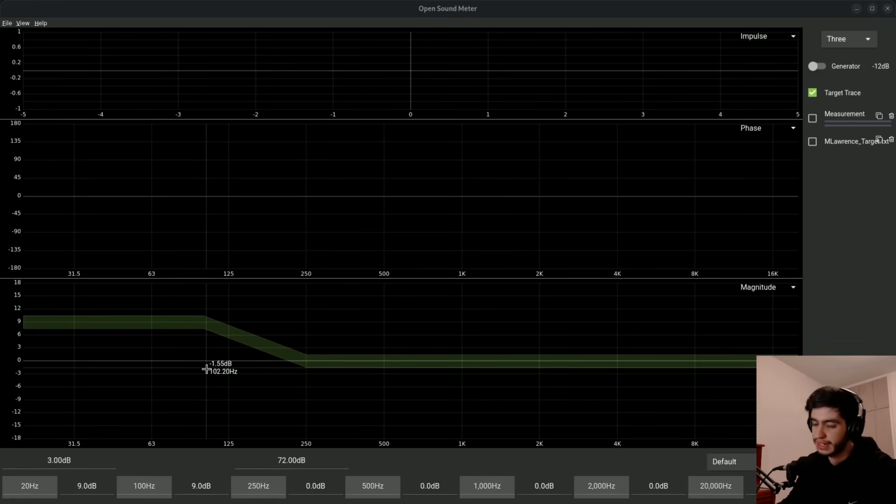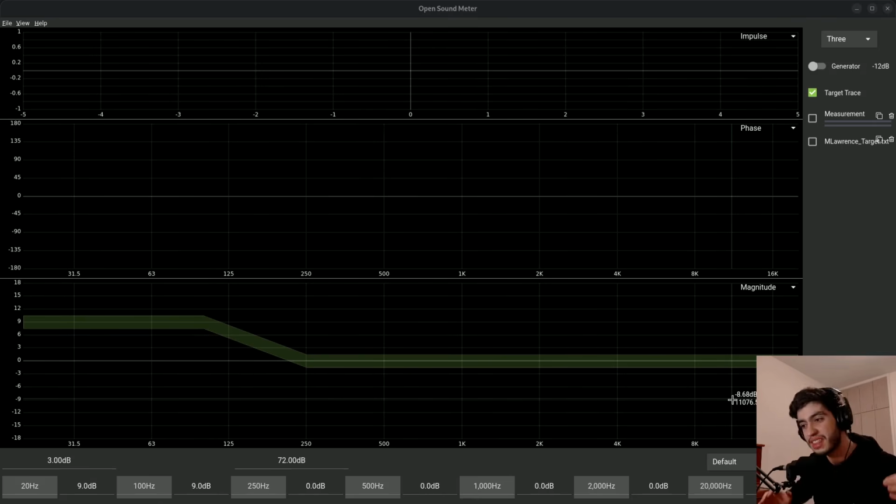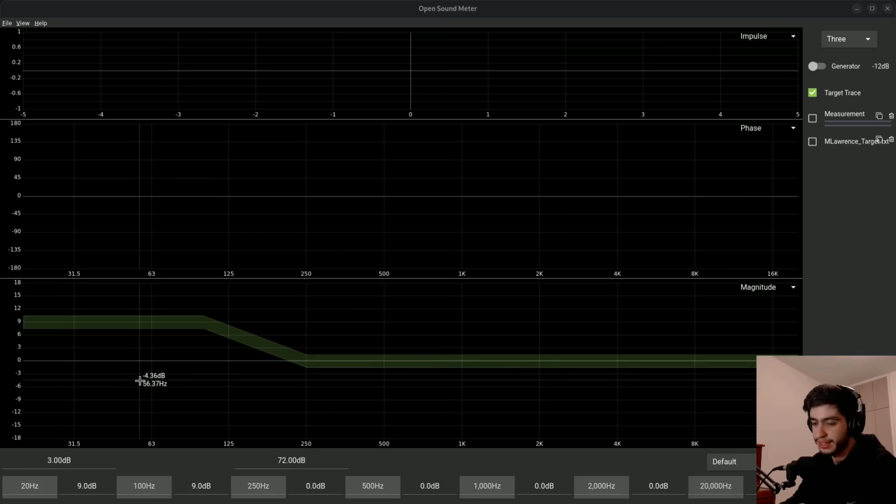And we need that in live sound because if you have everything flat, it will sound very weak because there's a ton more high frequencies than there is low frequencies. So for example, in these lower octaves from 30 Hertz to 120 Hertz, about 90 frequencies. But from 1 kilohertz to 16 kilohertz, there is 15,000 frequencies. So the low end needs a little bit of help.